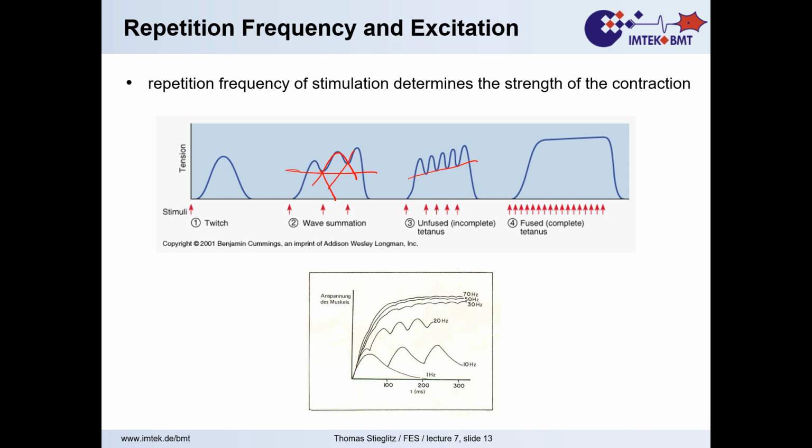I have my electronic circuit and the electrodes only active for 400 microseconds, while they are at rest for 19.6 milliseconds before the next pulse comes. And that's not too bad. There's a lot of time that electrochemistry can balance out, that physiology can restore activity, things like that, right?